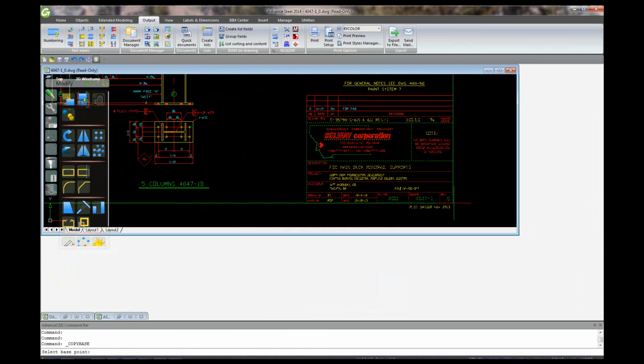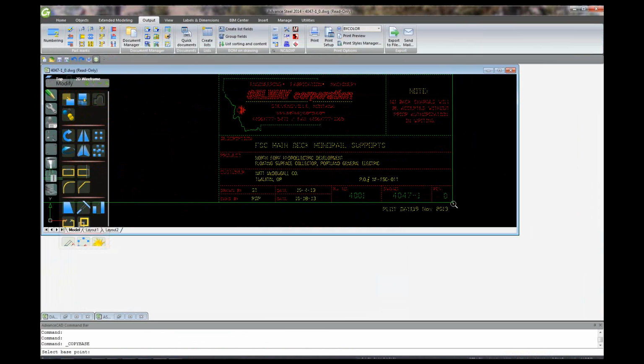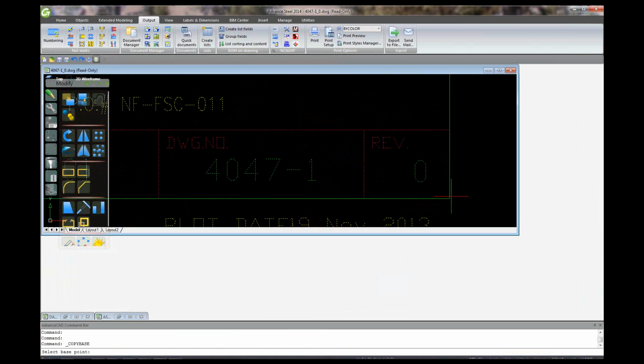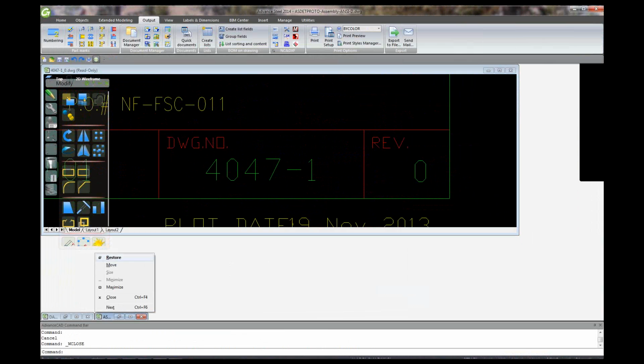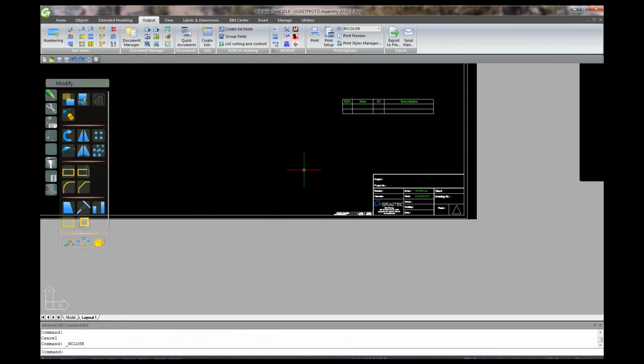Select that bottom corner, E and D to pick that. Okay. And enter. Select. All right, so go back now to your prototype, to the Advanced Steel prototype, that default one that you replace. There you go. Now right click.